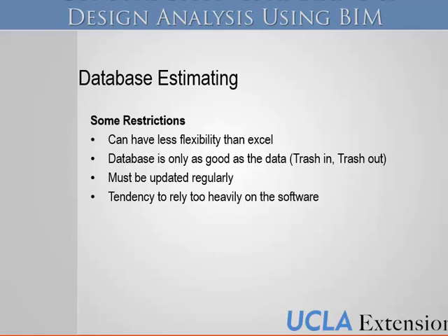Because a structural engineer is going to call out, I don't know, number 9s versus number 7 rebar, or add rebar along the way, or we have a case now where the building has double drywall in all these areas that the architect wants, and isomax springs for this, stuff that wasn't on the bid. So that's the art side of being an estimator.